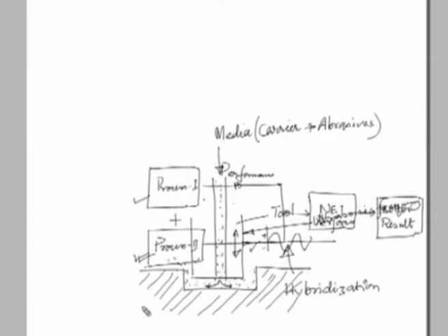In turn, the abrasive particles embedded on this media will get an additional motion, in the form of ultrasonic frequency, and which will get energized then and hit this workpiece surface at much higher velocity than it would have been with normal AFM process.